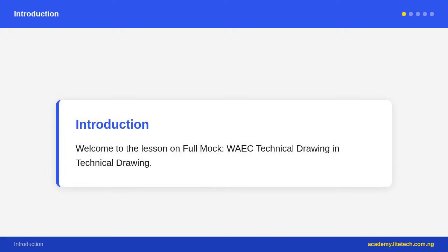Spur gear terminology. Module, M, the fundamental tooth size unit. Module equals pitch circle diameter divided by number of teeth. Larger module equals larger teeth. Pitch circle, the theoretical circle on which the gears appear to roll on each other. Diameter equals number of teeth times module.